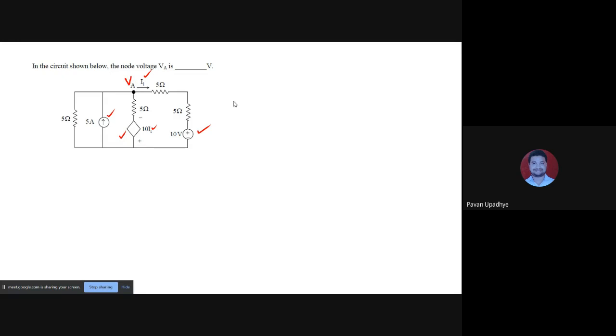So what can be done in such cases? So whenever you want to find the voltage, your first choice should be KCL or nodal analysis. Please remember this. Okay, this is a thumb rule that will save your time during examination. And whenever you want to evaluate current, you can think of KVL or mesh analysis, because when we write the equations for mesh analysis or the Kirchhoff voltage law equation, actually currents are involved.